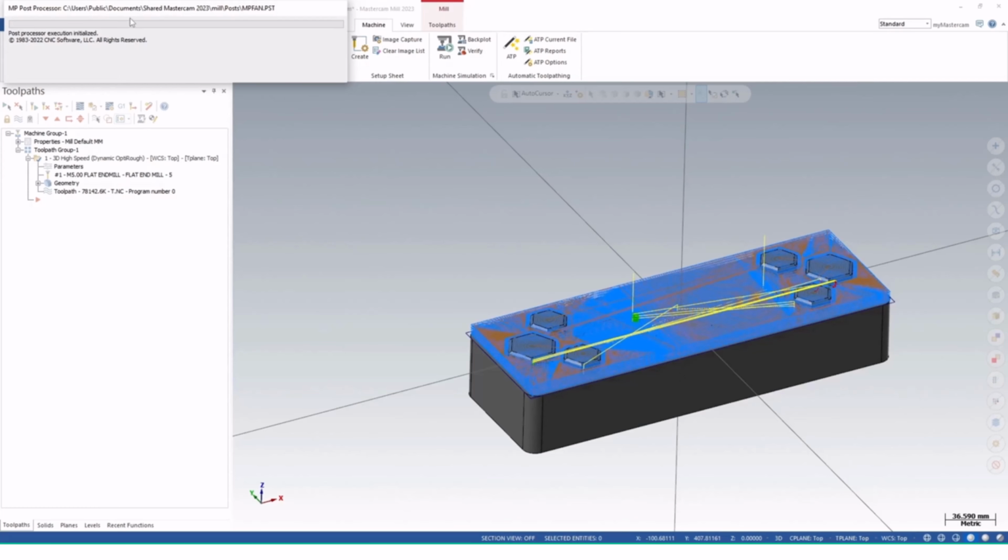The G code depends upon the settings, as you see that it takes too much time. This is because we have set our step over to 1.25 millimeter and the depth of cut to 0.5 millimeter. Therefore it takes a lot of time to generate the toolpath for all these depths and step overs.